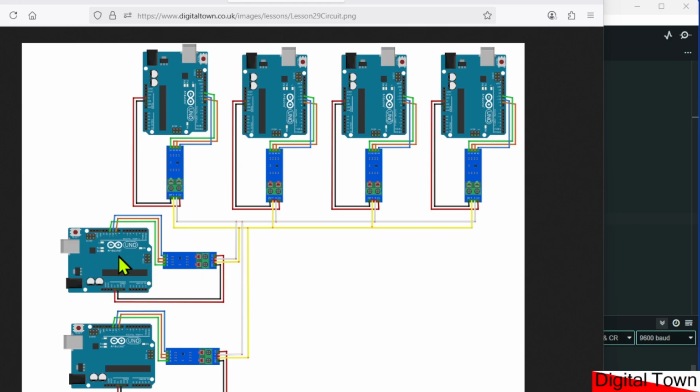This board will then receive that and go, oh, that's a ping for board 1. If it's got some data to send, it will immediately send its transmit pin high and transmit the data. Don't forget that data doesn't just go to the master, it can go to any of the boards. And as soon as it sends that data, it then shuts down its transmit pin.